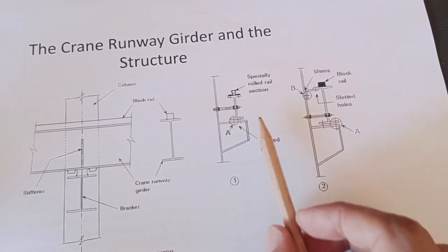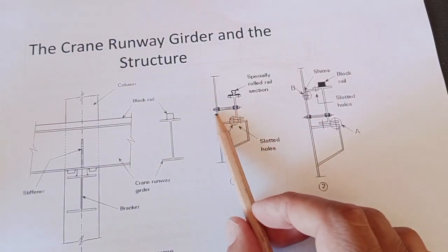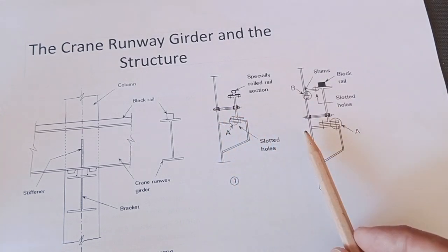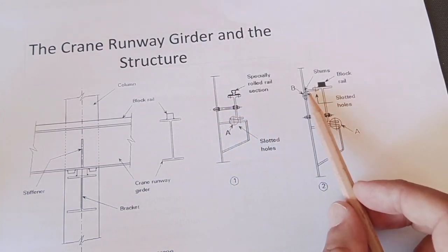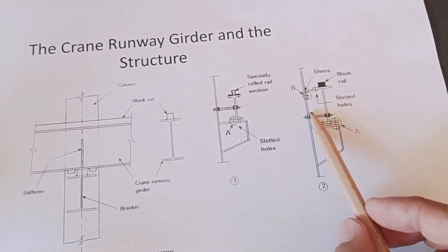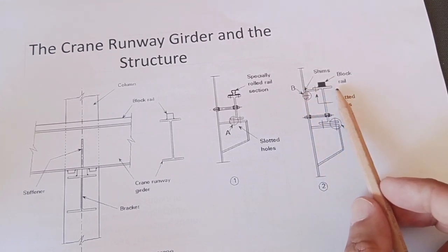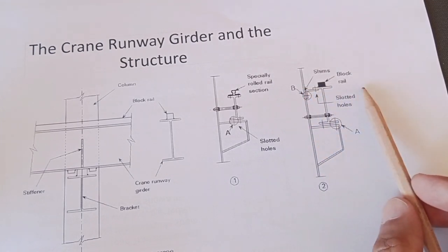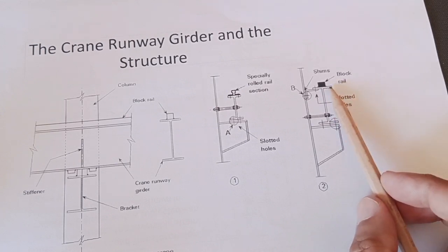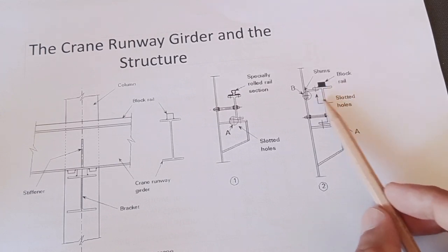You see that here it is connected from the middle. That is very dangerous. But if we have the top flange connected to the column, it is very safe for taking the lateral loads from the crane and crane bridge to this web.